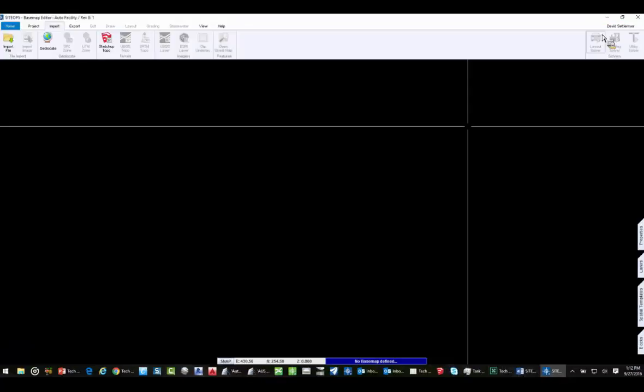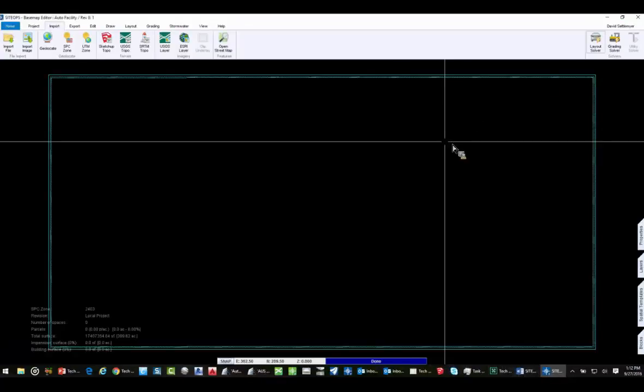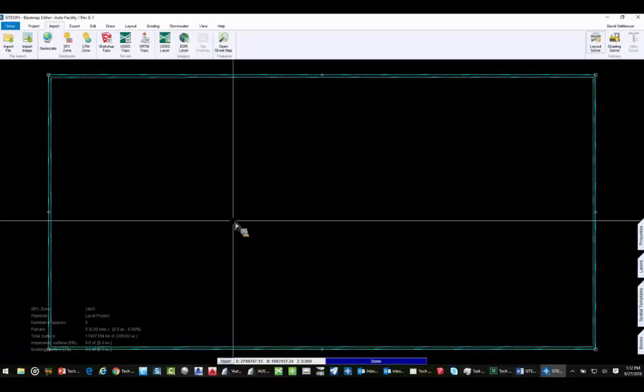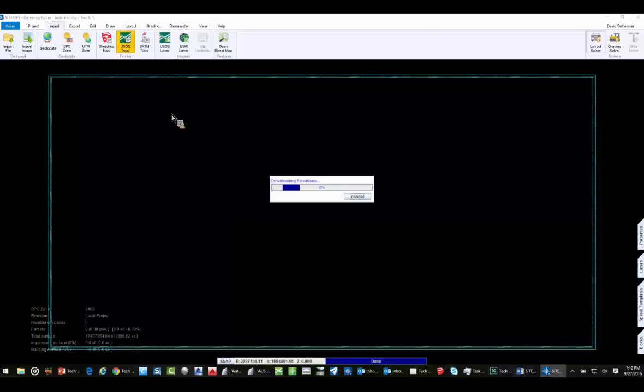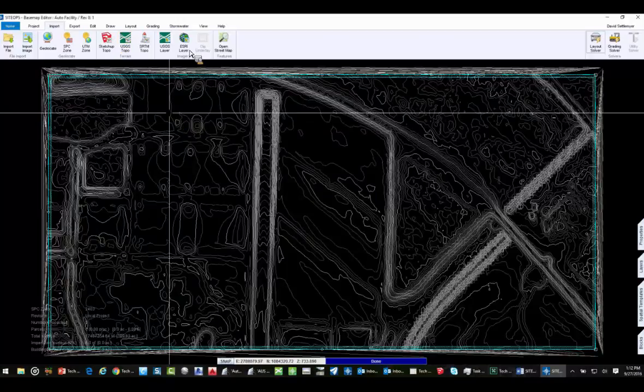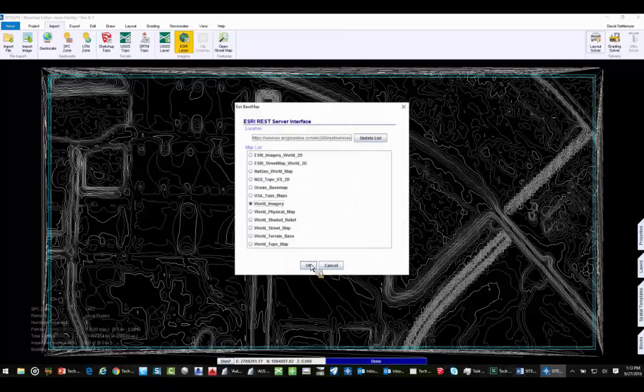So do select location. It's going to put the box on state plane coordinates for that region, which again allows me to start adding data. So for example, if I've already done SITEOPS and you went out and got a context capture model or they did a field topo, you can bring that in and it'll drop right into place. So let's grab some USGS topo. We give you the ability to come in from a couple different sources and get a model started. I also want to come in, do some Esri imagery. You know, all this comes with SITEOPS.